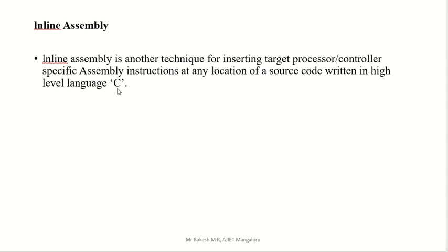Inline means that in the previous two cases, we are including high level or low level code in between, but that complete block is in one set. If we include 10 lines of assembly in C, those 10 lines are together. Likewise, when we mix C into assembly, the 10 lines of C are together in the entire assembly.